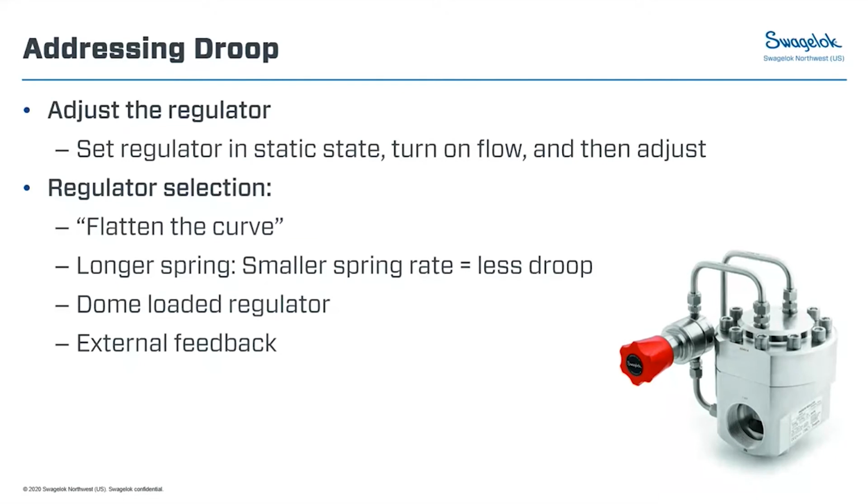Yeah, good. That's a really good question. So there are definitely regulators that have a venting option. Some will self-vent. So if you adjust the regulator to, let's say, decrease the outlet pressure, it can self-vent. If you're working with an inert gas, it could self-vent through the cap. If it's not inert, you can capture that vent and send it somewhere else.